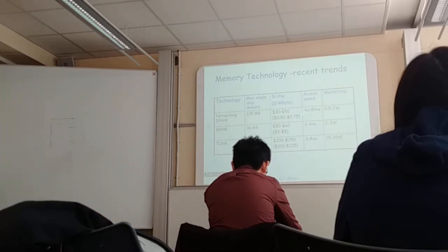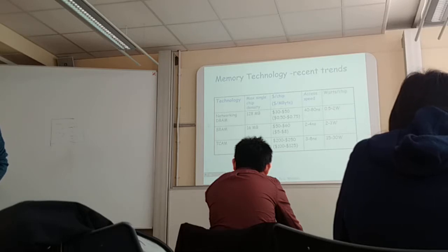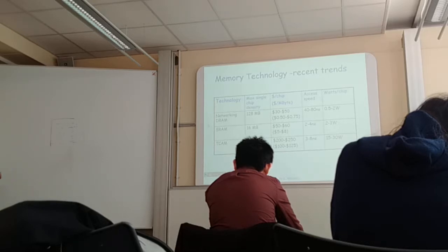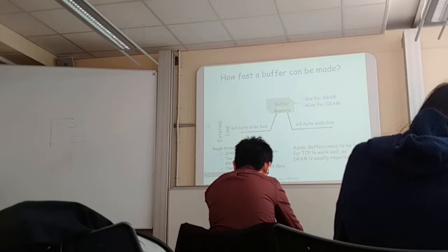No. Access speed is the speed at which you can access any location in the memory for a unit of data. That's the access speed. The memory bandwidth is how much data you can write to memory per unit of time for an atomic operation. In this case, if I have... Yes, that's exactly the point.